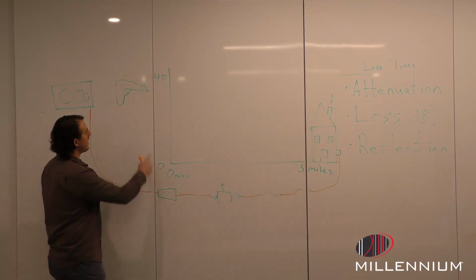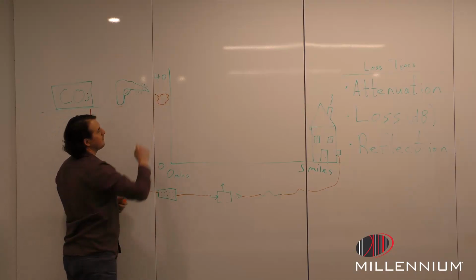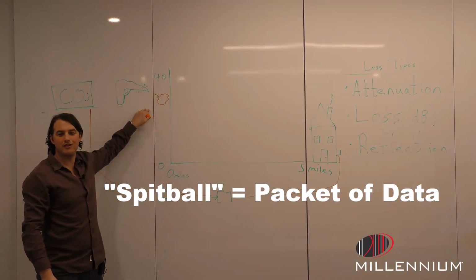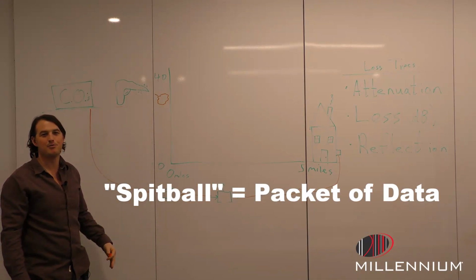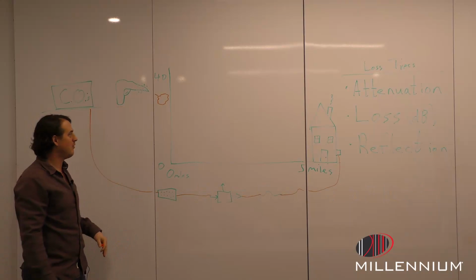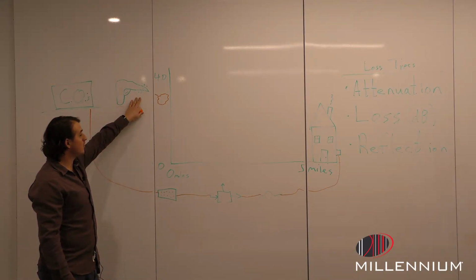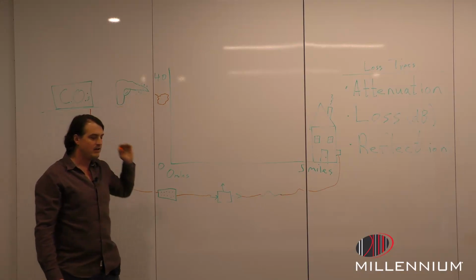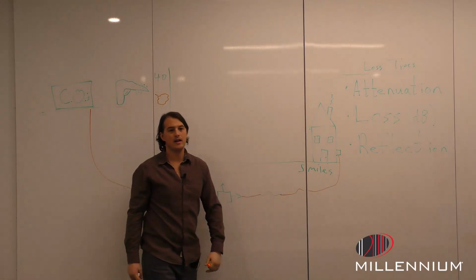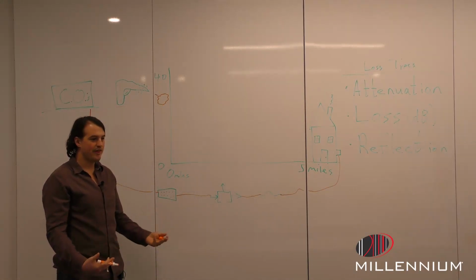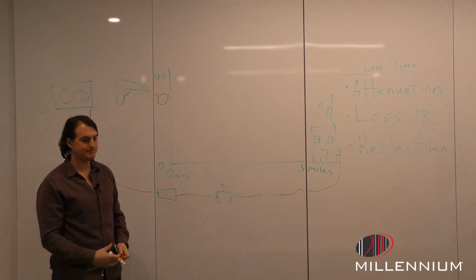If you are wondering what's going on with lasers and spitballs, there's another video that will introduce you to the principles behind wavelengths and light. So the OTDR shoots a spitball, and it knows how fast this spitball is going to travel down this network. And it's timing it. With that, it knows how far light has traveled.